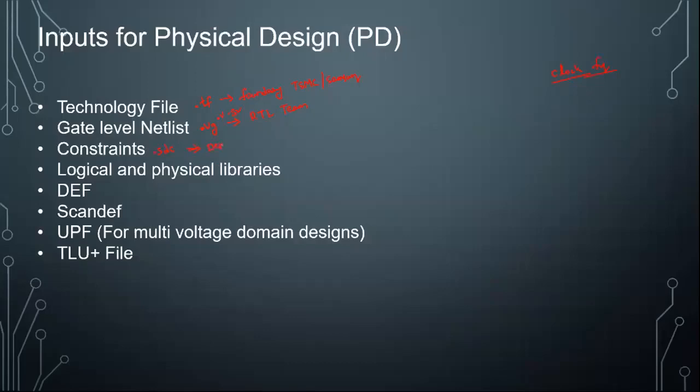If you are a designer, you can decide. Majorly we need to discuss with the specification team and understand what the requirements are. Accordingly we'll go with the constraint development. In the SDC we have create clock, input delays and output delays. We will even estimate the delays also.